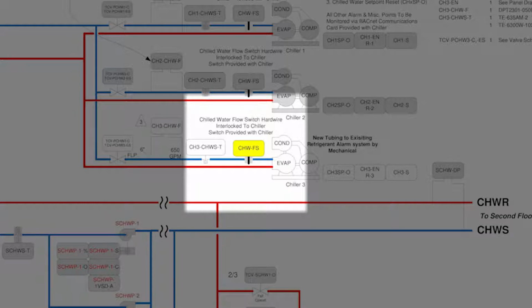And when we go to the HMI screen and the chiller guy's with you, he's going to go through that. What are the numbers of flow we're looking for through the chiller barrel? I don't know what the minimum is. Below that the chiller will stop. I'm not sure, but I'm going to say it might be 168 gallons per minute.